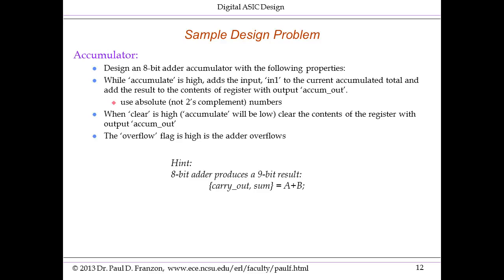And of course, with unsigned numbers, how do you detect an overflow? If this carry out becomes equal to 1, that means you've overflowed. So at this point, I think it'd actually be useful for you to stop this recording and actually try this design example.